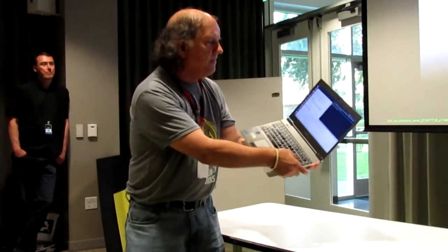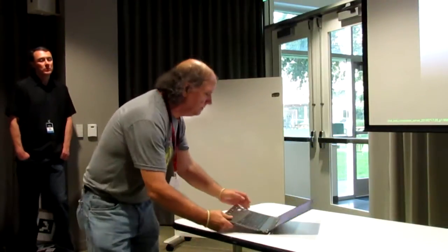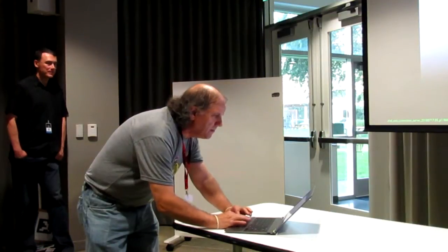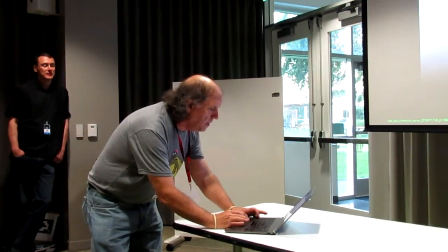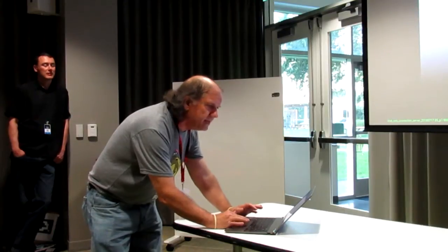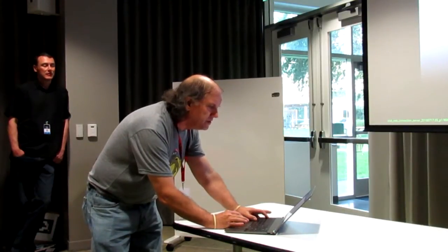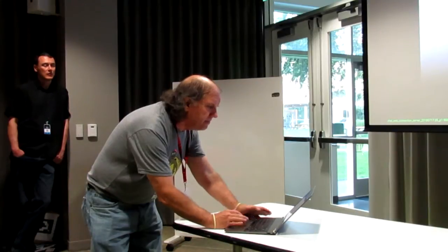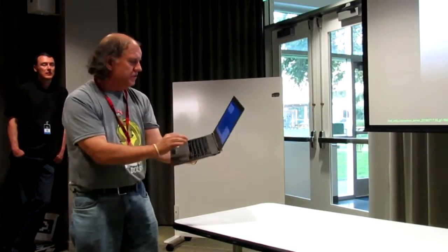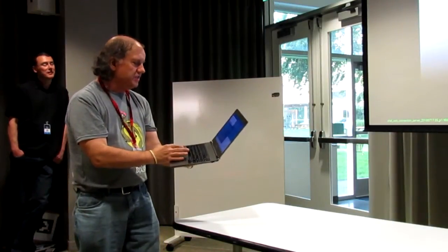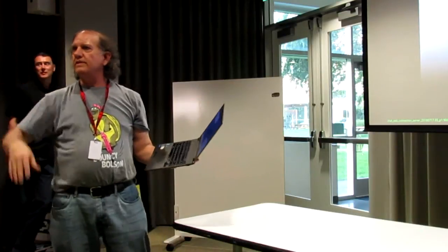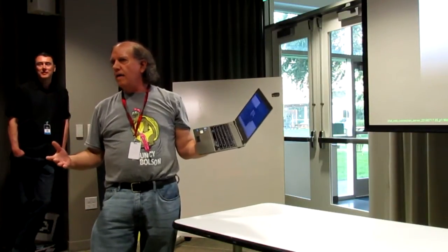So now I'm going to save this map. The map has been saved, and I'm going to load in the navigation stack. The navigation stack in ROS, Robot Operating System, consists of 2 components, the path planning and the localization. Path planning is called Move Base, and the localization routine is AMCL, Adaptive Monte Carlo Localization. So I'm going to kill the gmapping, the grid mapping routine, and I'm going to load in the navigation stack. Ralph Gnadinger has written these marvelous launch files that load a couple of ROS nodes simultaneously, so it makes it easier, okay?